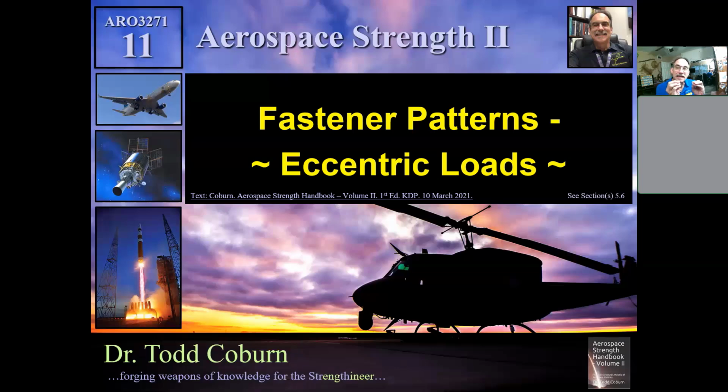Today what we're going to do is look closer at all those fastener analyses where we're looking at lap shear or double shear fasteners, which were the simplest of fasteners. So if you're still throwing away those points, you're going to want to study those joints so you understand how to calculate the appropriate loads. However, we're going to find out that those are the simplest, and whenever we have what we call an eccentric fastener pattern, where the load does not pass through the centroid, it's actually a little more complicated.